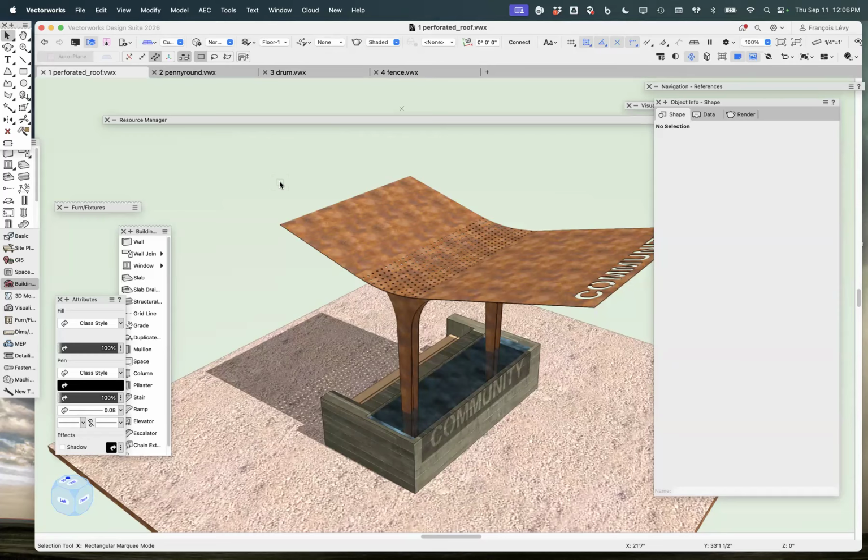All right, so once I've got that geometry, in this case it's a shell, but it could be anything. Under my 3D palette, there's this extract feature. You can extract points along an edge or extract a single curve, so an edge in this case, or face is what I want to do. As I'm hovering over this shell, it's highlighting that face. So I'll just click on it because I'm in the face mode and hit OK.